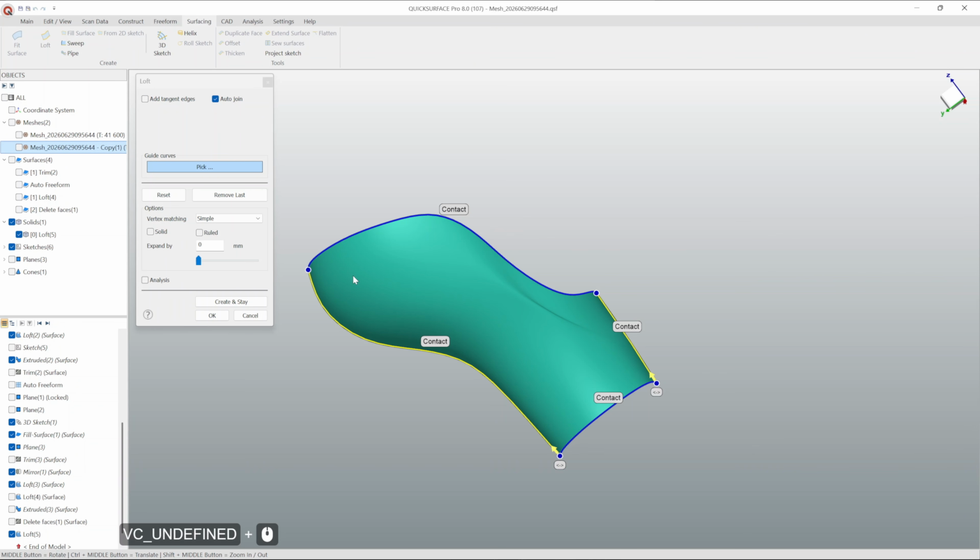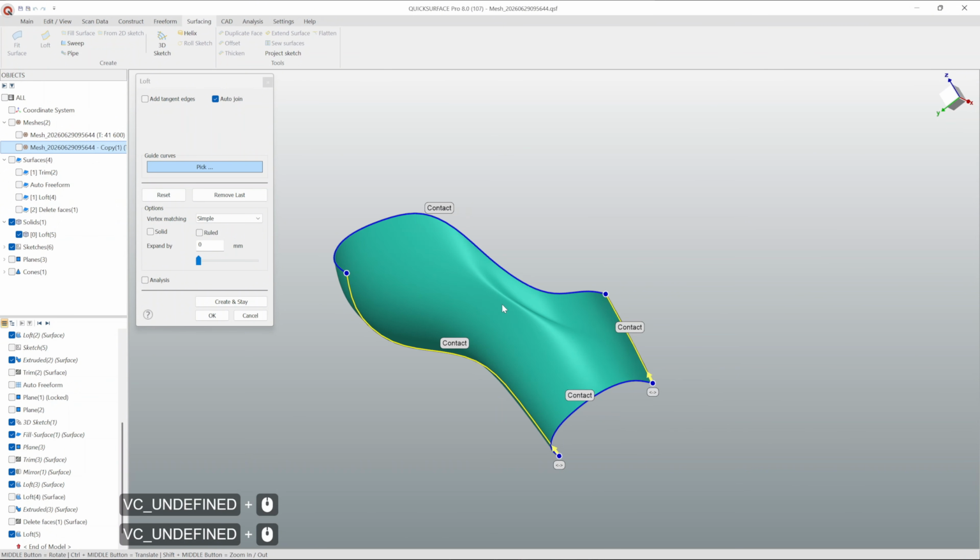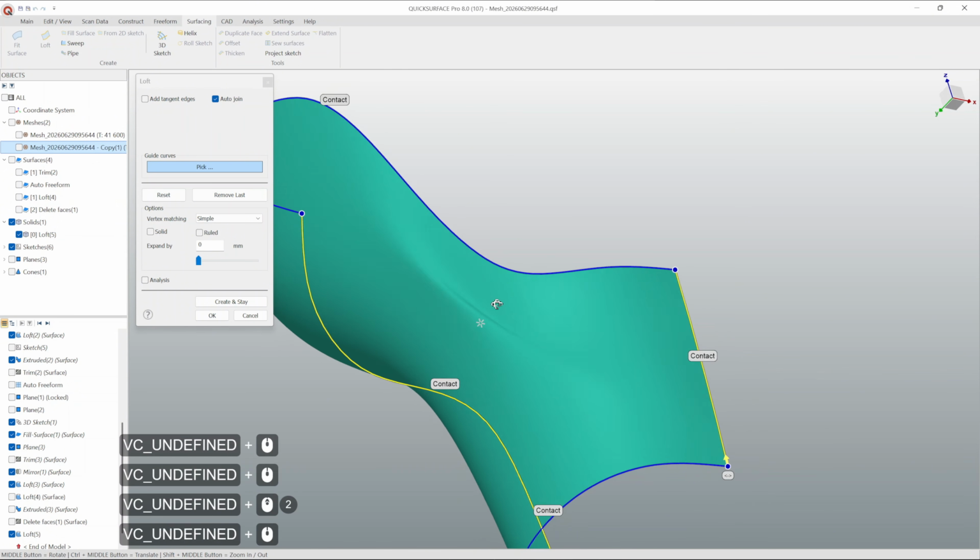And since all of these guide curves start to curl quite a lot, like this, and the same goes to this one, somewhere from here it tends to create the guide curve that we don't see, the middle guide curves inside of Loft tool itself. It starts to create it more or less perpendicularly from this edge here, from this curve, and tries to match it perpendicularly here. And this is the reason why we are getting all of these weird results here.